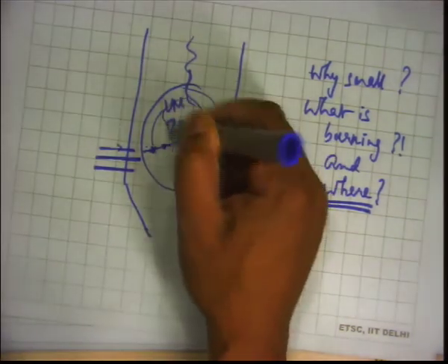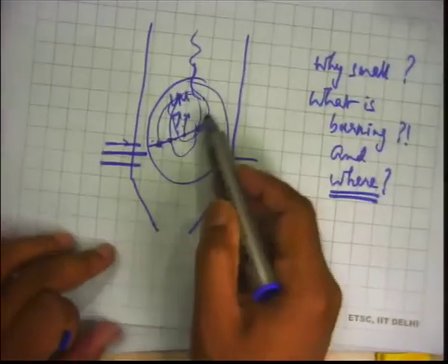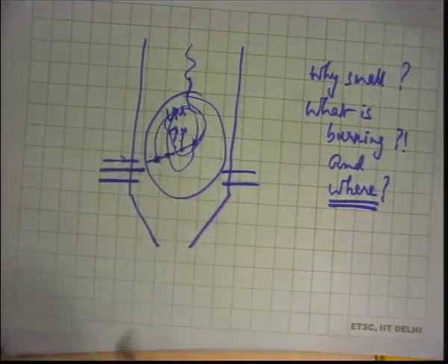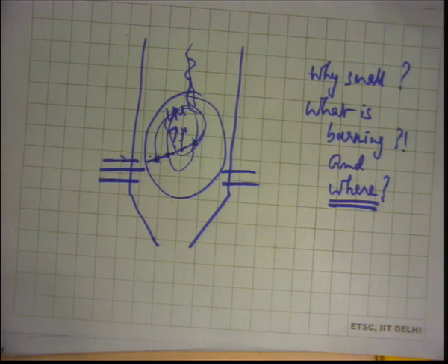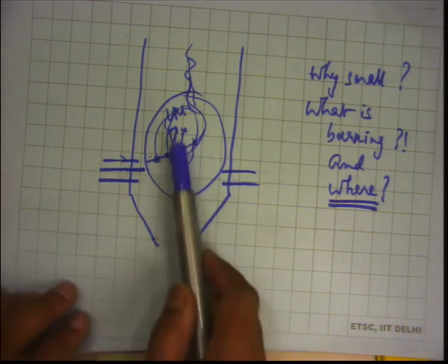The volatile matter combustion will be closer to the burners. It's an earlier stage. Char combustion will take place later. It's sequential, remember. Small particles are burning sequentially. Which process takes the maximum amount of time? The char combustion process. And that is the reason the boilers are so tall. Boilers are so tall because unless you give them the space, the char will not burn.